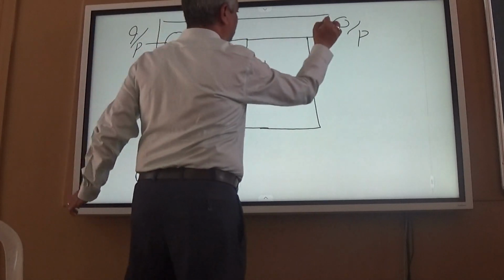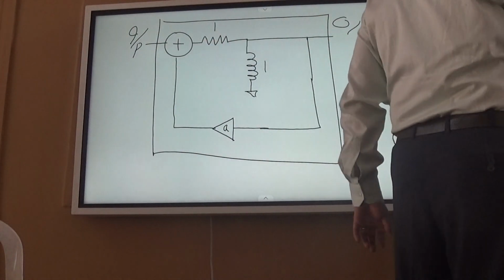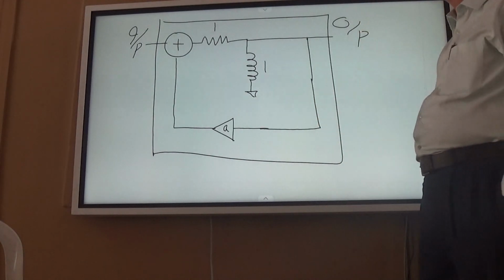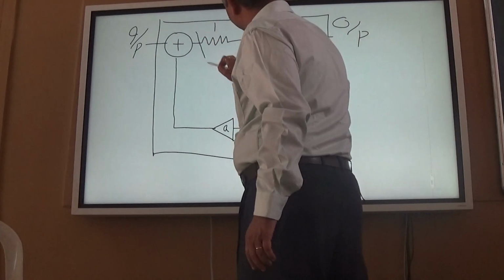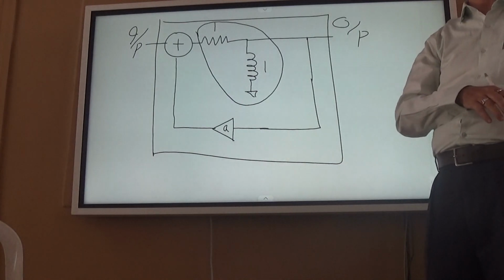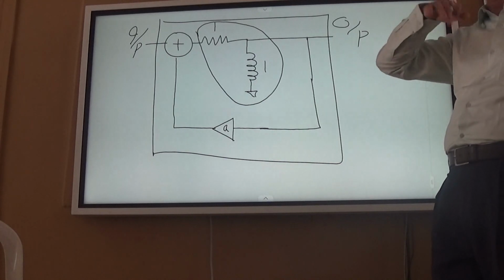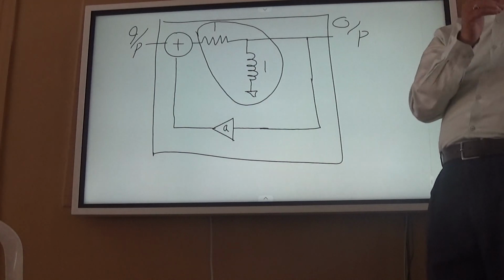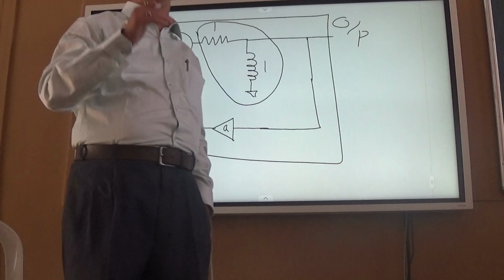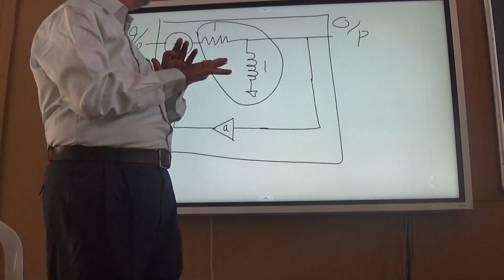So let me check whether you are able to do that. Be quick. So I will now stop. I will go along with you. So what is this transfer function? There is no need for us to develop the differential equation each time. The inductor impedance is Ls, capacitor impedance is 1 upon Cs, and resistance impedance is R. So with that we are able to find out.